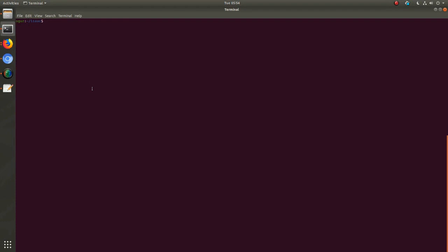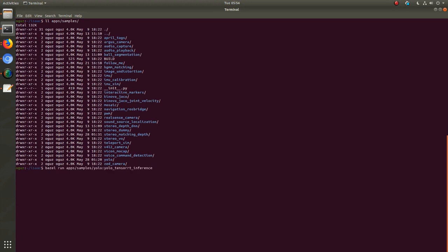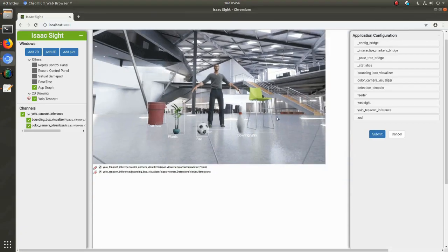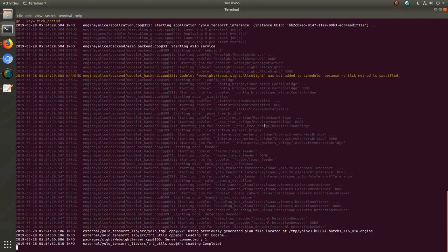Isaac provides you with powerful and easy to understand sample applications. In particular, let's run the YOLO inference app. On site, you'll see that Isaac is detecting various objects from an image. Instead of a fixed image, you could also supply a video from Isaac Sim or any other simulation of your choosing. You could also use YOLO Inference app in real applications as well, perhaps to generate some goal. The same sample folder also provides an application for training. You can either train in reality or in simulation.